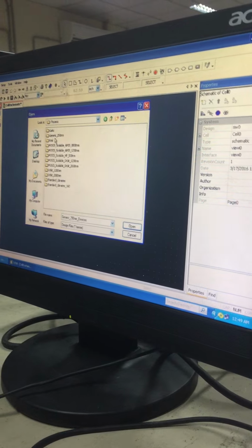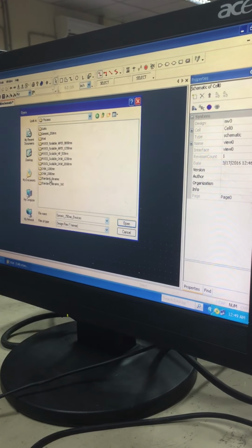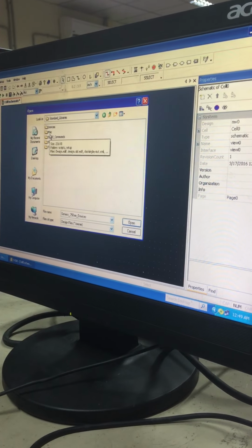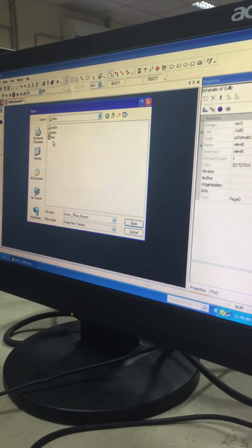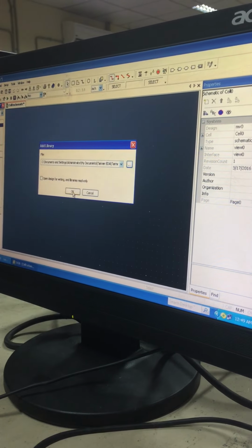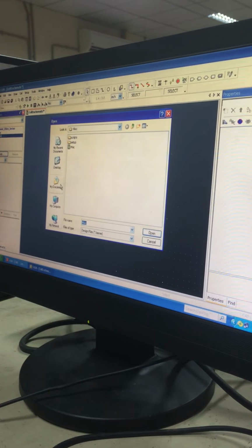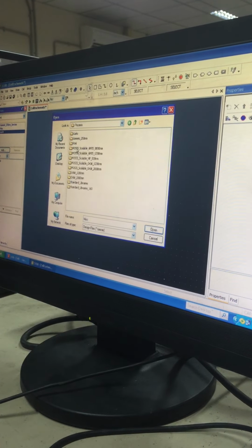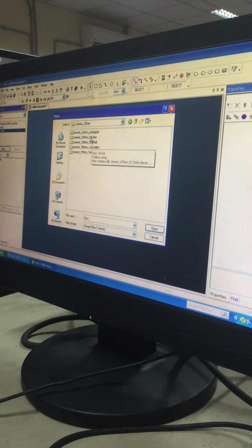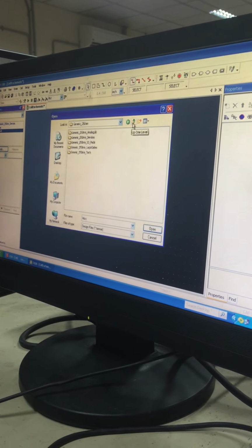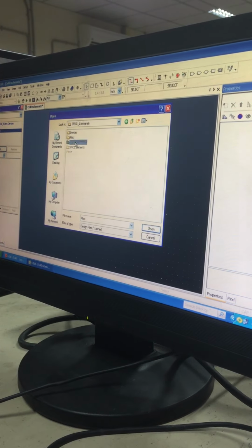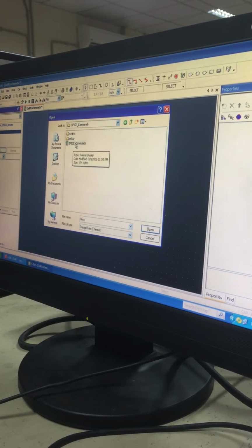First in add you added generic 250 nanometer. Now you go to standard libraries. Next you have miscellaneous. Each and every time you have to do it separately. You have to add each and every component separately by browsing the path. Tanner EDA, Tanner Tools, process, 250 nanometer, and in that standard libraries, miscellaneous. Similarly, you have to open spice commands.